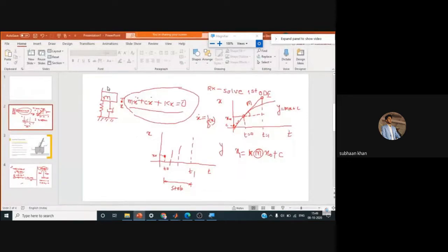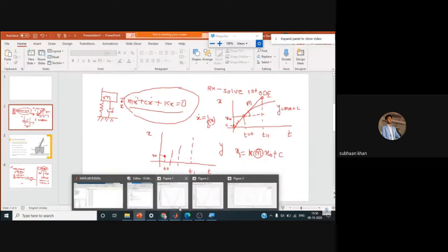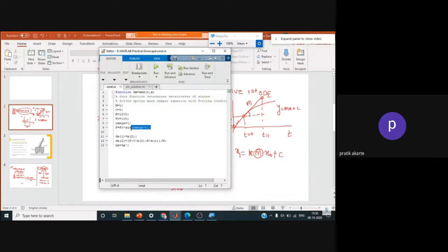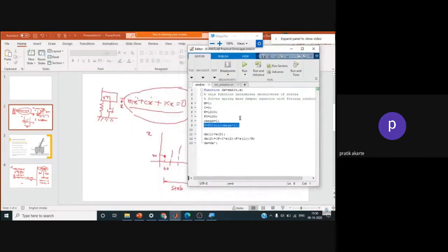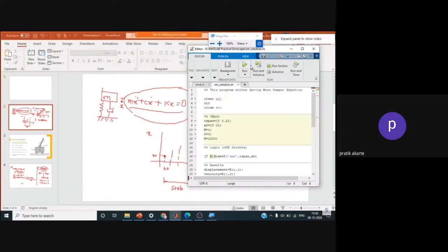If I put a motor onto this, the motor may have a certain unbalance. Due to this unbalance, the force is going to be sinusoidal in nature. That can be simulated, or approximately treated, by the equation F equal to F0 sin of omega t. Instead of 1 radian, I will put 5 radian, and I will have zero damping in this case. Then I will start simulating.